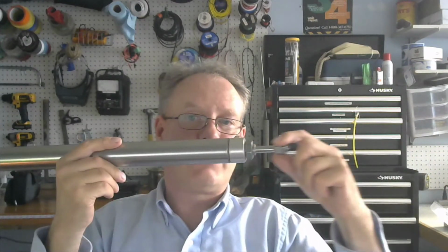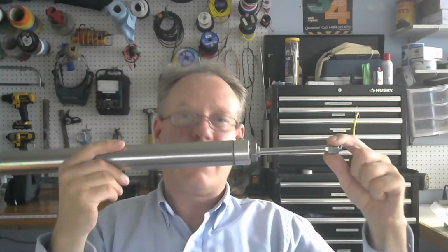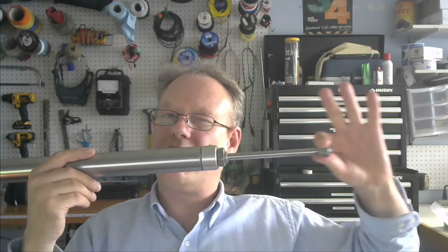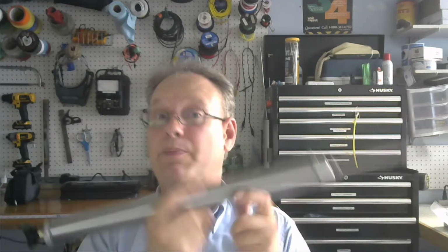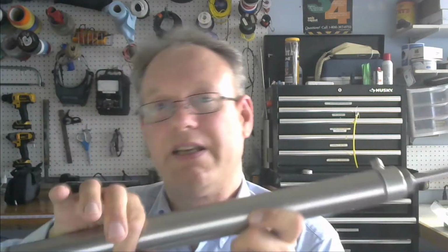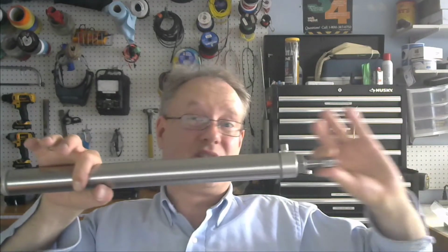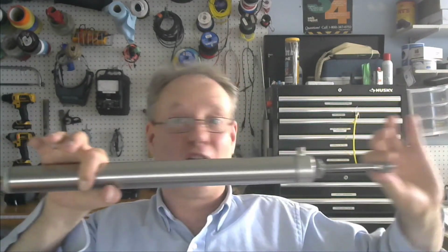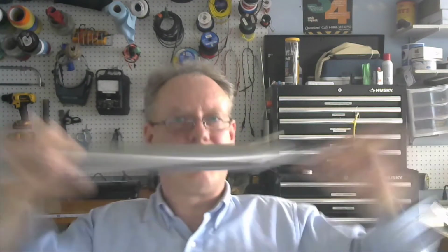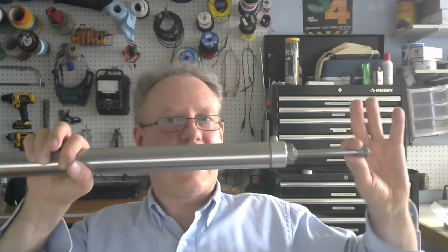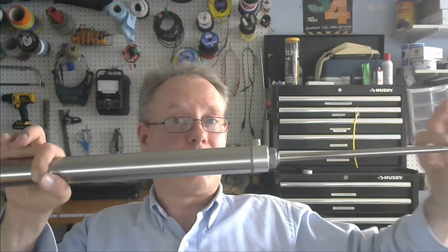So because the volume increased, the pressure went down slightly. And this thing is going to then jerk a little bit. It won't be a nice, smooth, even motion. It may show just a little bit of jerking, especially if the seal in here is really an older seal or doesn't slide that well. I mean, most seals are pretty good, but I've had this cylinder for 10 years, so the seal's probably not good in it anymore. I've been using it for demos all over the place, so I'm actually probably destroying the seal. So this thing actually might jerk a little bit if I put a little bit of pressure in here to make it extend.